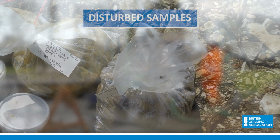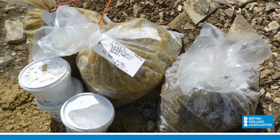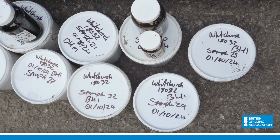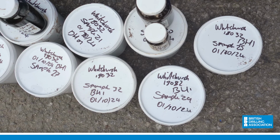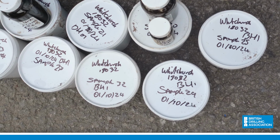With all disturbed samples, it is really important that if different strata is encountered, that materials from each strata type are kept separate and recorded as separate samples, even if the size of the sample is less than the ideal weights previously mentioned.